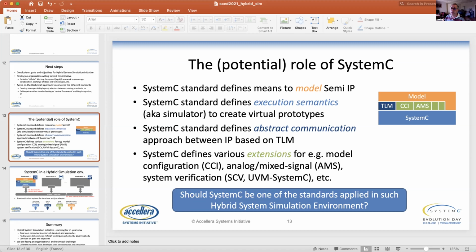But at the moment, I think one of the things we are sorely missing in the SystemC community is an external API. And I think that's evidenced by the pain that we're currently going through in the language working group, and the so-called unsuspend interface is part of this story, giving us a mechanism by which we can at least synchronize with the outside world. And I think we are probably at a point with SystemC where having some sort of external interface, so that you don't wrap up VHDL inside SystemC, rather you have a way in which you could communicate with an external VHDL simulator or an external hardware in the loop, would make some sense, and we don't currently have that.